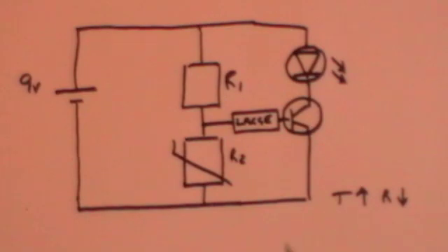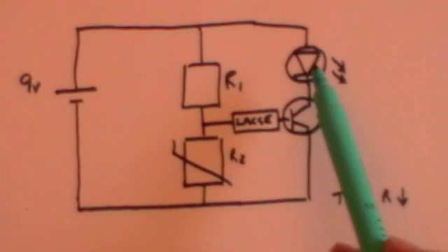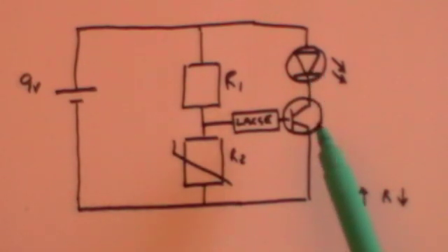So this is a device which uses the transistor as a switch, such that if the temperature falls below a certain value, the light comes on. So this is potentially a means of operating a thermostat to turn the heating on when the temperature falls below a certain level. And the transistor participated in the logical decision of whether or not to turn on the heating. And transistors are, or at least were, at the heart of logic circuits. These days they're designed in a different way, but for our purposes we're learning how they used to work, using individual transistors in a combination in order to provide logical outputs.